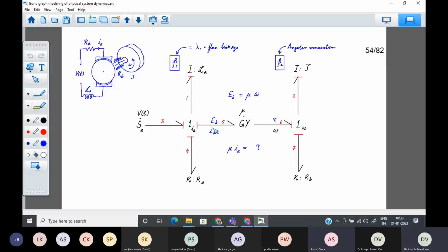And you have the electromechanical action due to the motoring action, due to the electrical side, resulting in the development of a torque, and that drives the mechanical side. So the rotor starts to rotate with an angular velocity of omega. J is the moment of inertia associated with it. And we have also considered joint bearings here with RP as the damping associated with this.